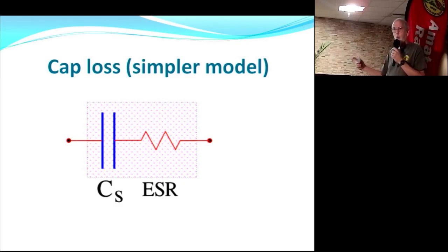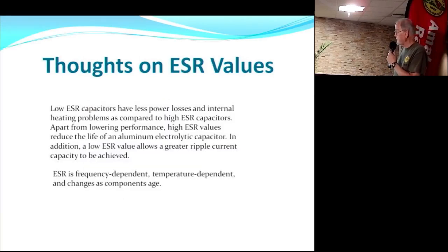And the heat and a liquid. What happens when you boil water? Well, you got an electrolytic in there, maybe rated for 80 degrees or 90 degrees centigrade. You keep heating it up and it's going to go away. It's going to dry up. So that's why we do have a meter back there, and we're going to show you how to use an ESR meter so you can figure out what does an electrolytic capacitor typically have for an ESR.